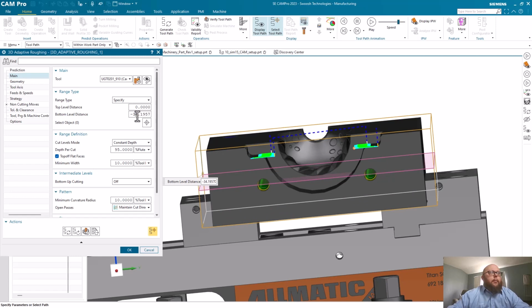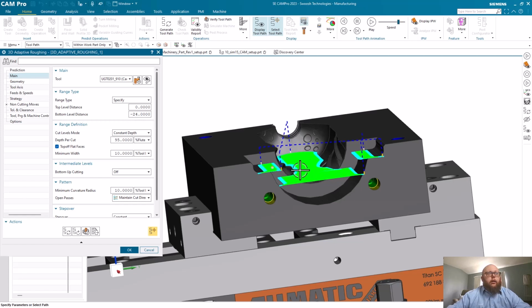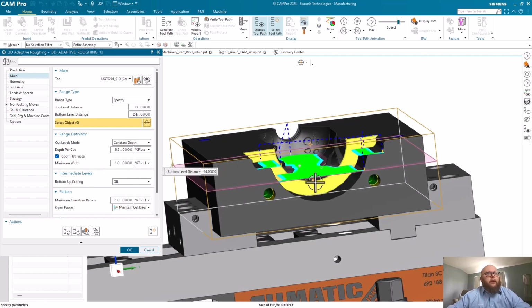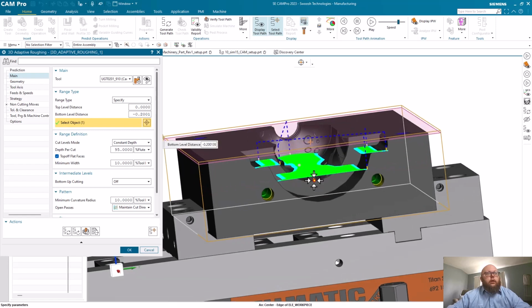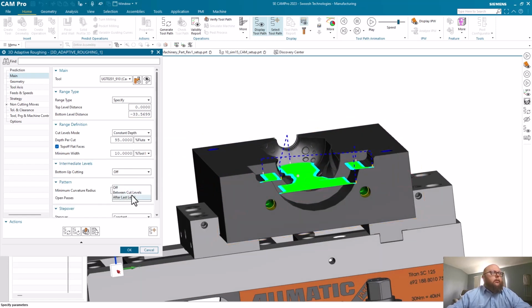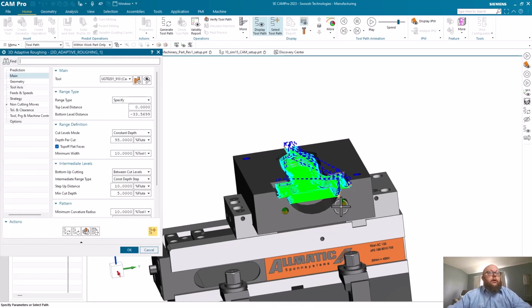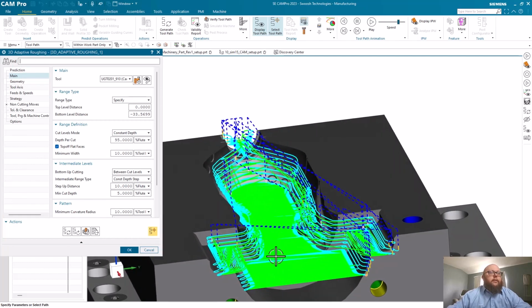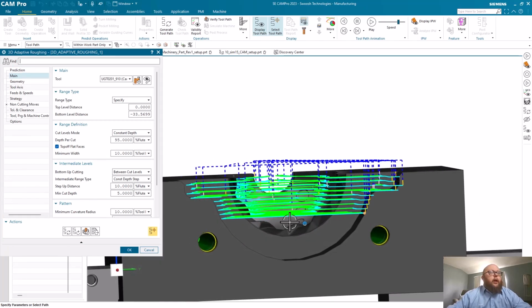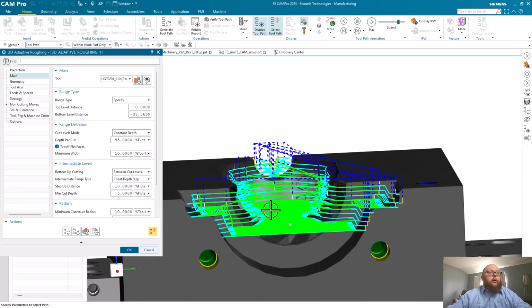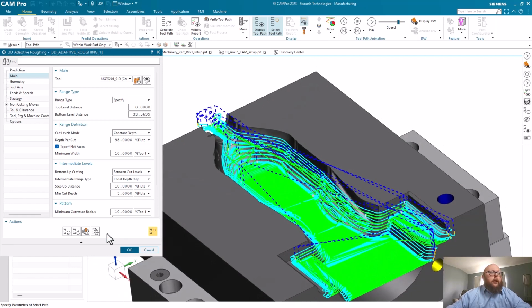So this is where you may want to come in and put some numeric values in here. You can see here with the negative 24 value, we can achieve the toolpath that we likely would want. Okay, so maybe we don't want to play with these numeric values. This is where we can still use our bottom-up cutting, and I'll leave the default values. We'll just generate those and still cut the regions as you may expect. So you can note just how quickly these toolpaths are now generated. With bottom-up cutting turned on, we're able to walk all the way up these walls as one might expect.